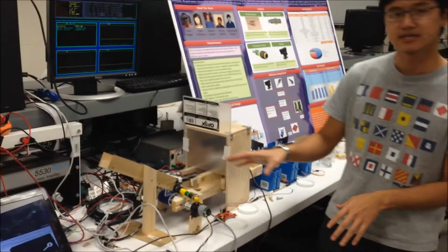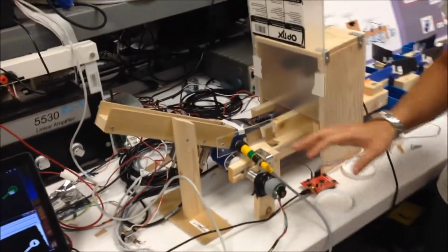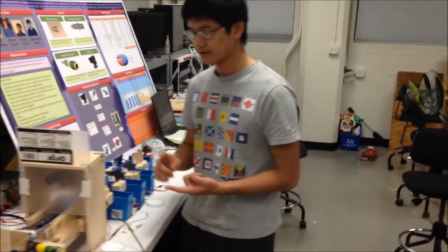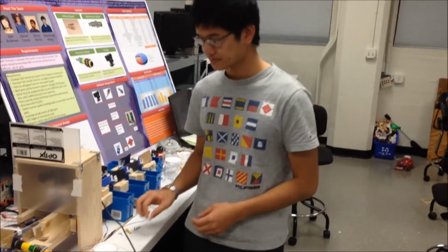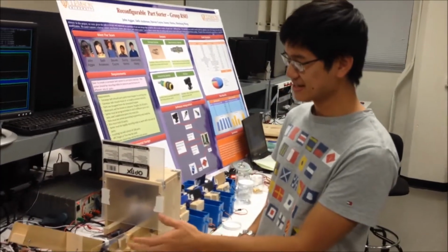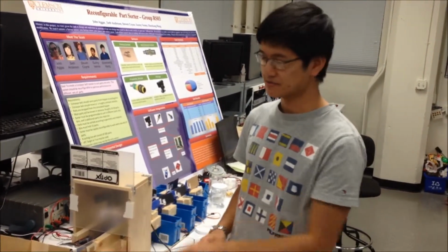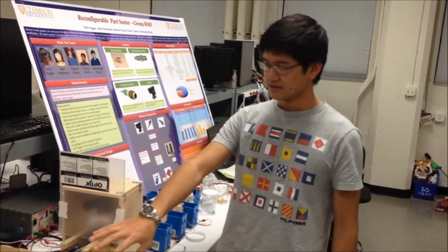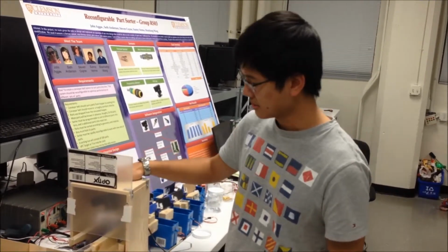So the first group of sensing, shown here, is embedded in our hopper system, and it consists of 3 proximity sensors. These 3 proximity sensors will sort the pieces based off of whether it is ferrous metal, a non-ferrous metal, or not a metal at all, so these plastic pieces here. After that, based off of the data gathered in this group of 3 sensors, this data is sent to our camera and the C code that controls our camera.